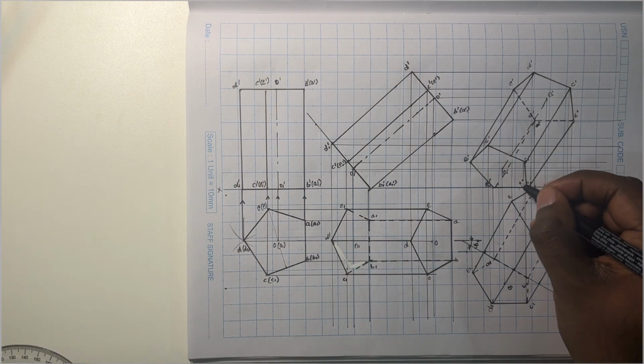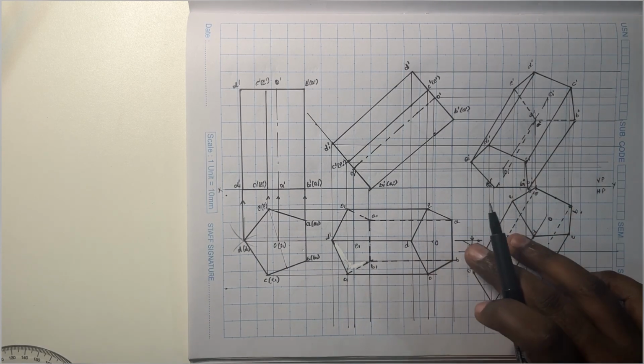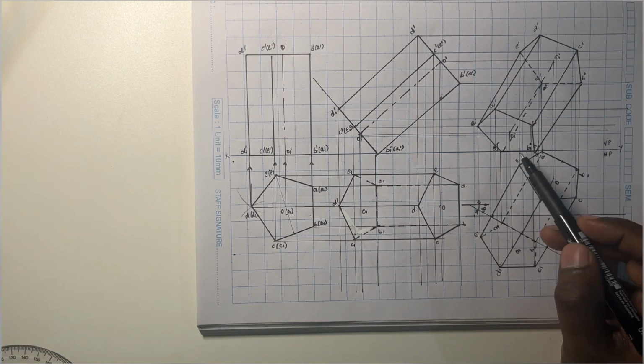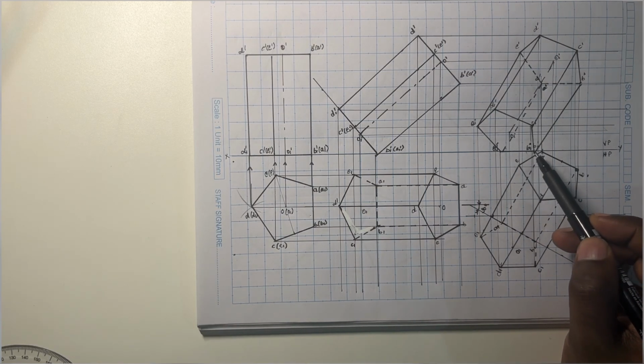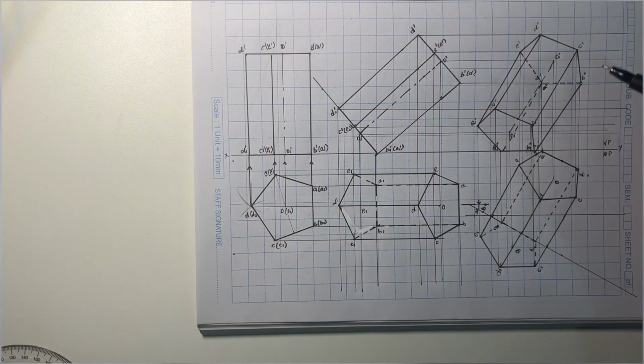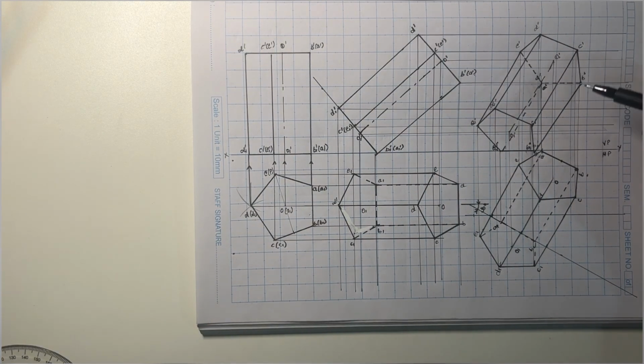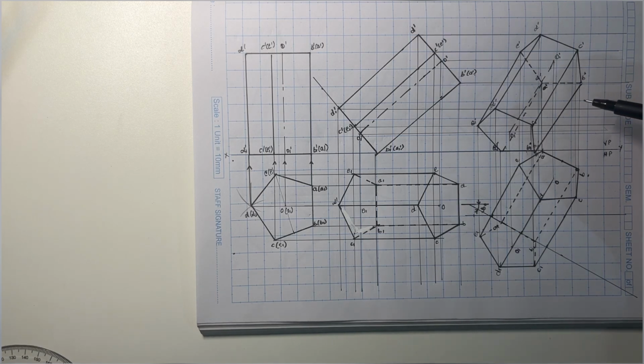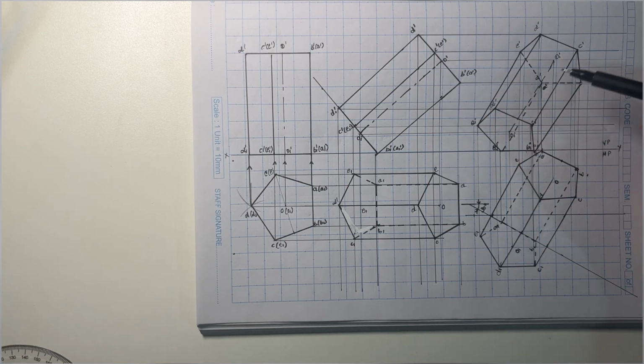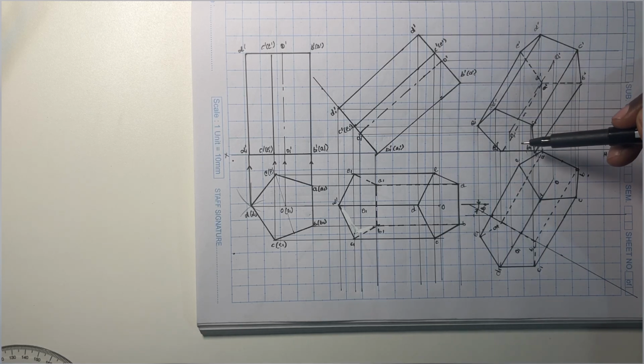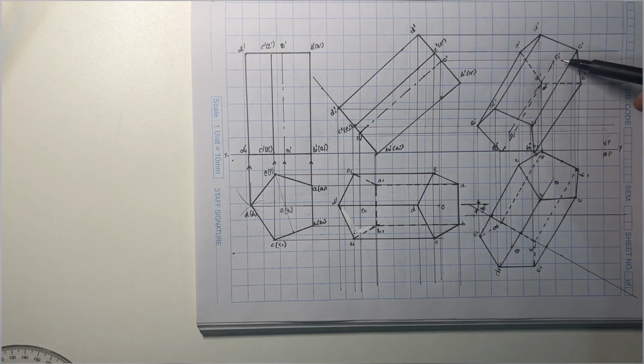So how do you validate this if it is correct? So initially it is resting on which edge? A1, B1. In the final position also it is on the edge A1, B1. So with this we complete the problem. So you can just see that A dash to A1 dash is hidden, A dash to E dash is hidden, A dash to B dash is hidden, and rest are all the thick lines or the continuous lines which are visible to the observer. So the bottom face of the prism is completely visible, whereas in the top face only these outer edges are visible, and this edge is not visible, so it is in the dotted line, and O1 to O is the axis in the final position.